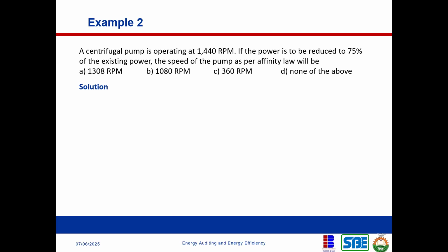You don't necessarily need to change the entire motor. You just need to change the pump, so that it can align with the load that it has. If this happens and the motor is already oversized, it is also recommended that the motor be fitted with a VSD. So you can vary the speed of the motor, and then you can properly dimension the pump that is required based on the load.